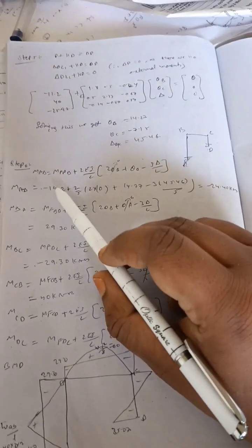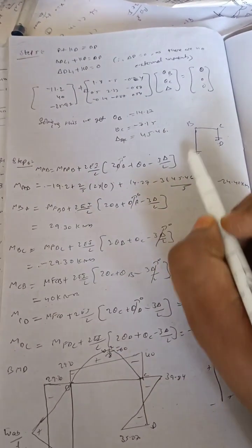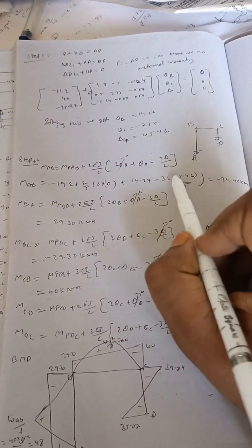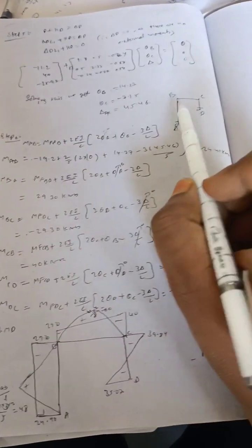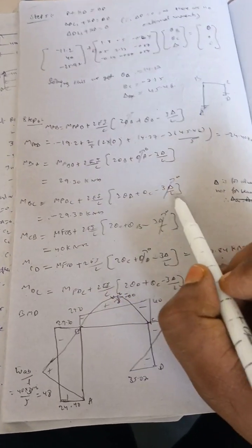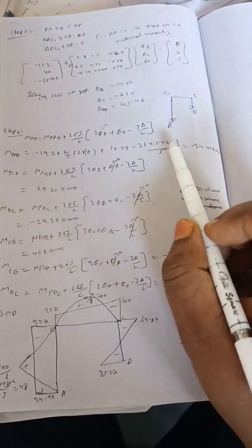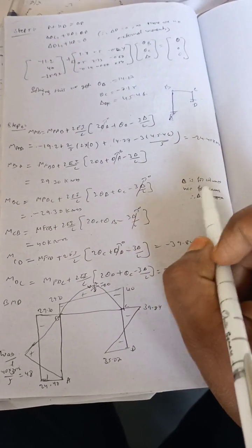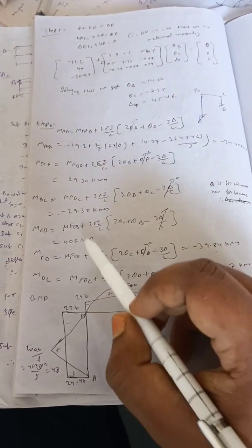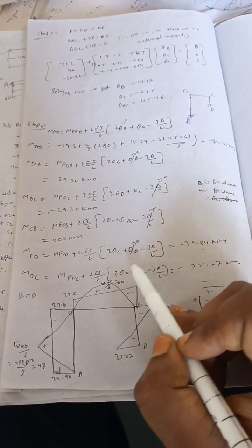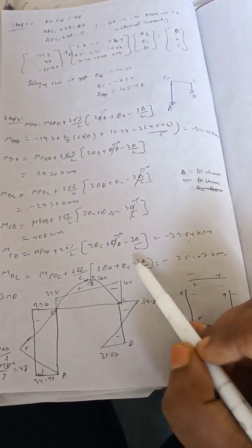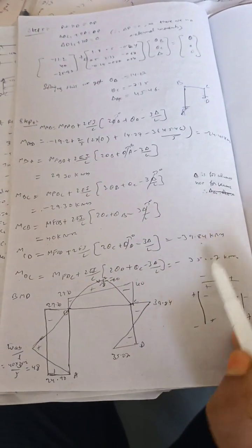Okay. And for AB and BA we will get delta here. Delta we have to substitute this value. See, for BC and CB, there is no delta value. Delta value substitute 0 because we know that sway is only for columns, not beams. BC is beam here. Okay, only for columns, not for beams. Next, for MCD, in the MCD formula, delta D will become 0. Then you substitute values, you will get this one.